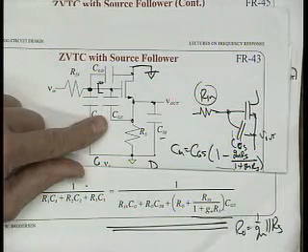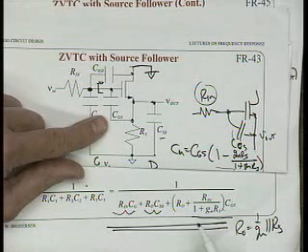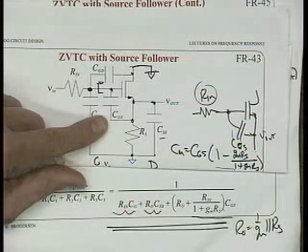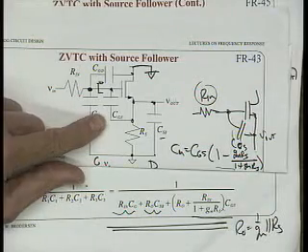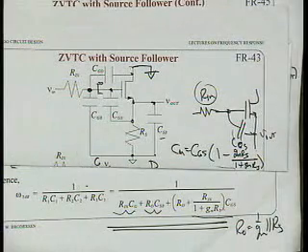One of them's dominant. You can look and try to see, is this the dominant one? Is this the dominant one? Or is this part here the dominant one? And you can sort of figure out which of the nodes you need to work on to increase the frequency response of the circuit. That's it. So that's zero time constant analysis.